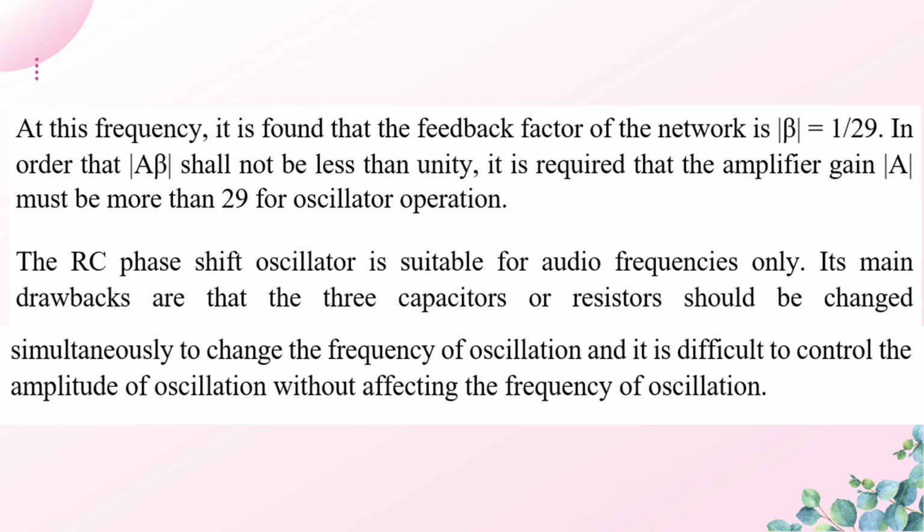The RC phase shift oscillator is suitable for audio frequencies only. Its main drawbacks are that the three capacitors or resistors should be changed simultaneously in order to change the frequency of oscillation, and it is difficult to control the amplitude of oscillation without affecting the frequency of oscillation.